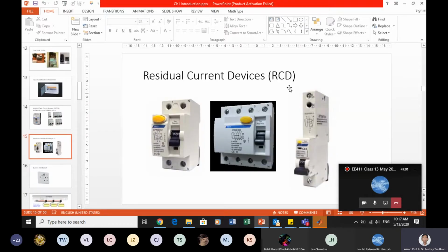And then this RCD, like I say, RCD is a device that comprises RCCB and this RCBO. Now you will see, how come RCCB only has something like one line? In fact, it also has live and neutral. Usually they will have one wire coming out for you to connect. Like I say, it needs a neutral line to work. This is simply because of a design that combines both together to save space.